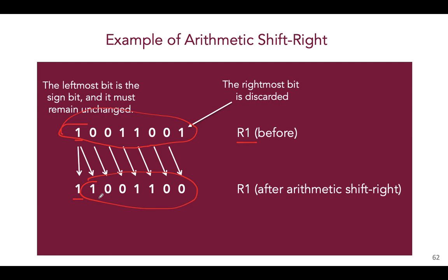And then since you have 9 bits and you wanted 8 bits, you just drop one of the bits, right? So first you copy the first bit as it is because the sign should not change, and then you copy this entire number again, 8 bits, you copy them. This will be the result you get. And then since you only need 8 bits, right, you discard this one, and that is arithmetic shift right.